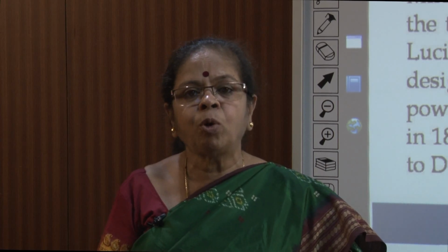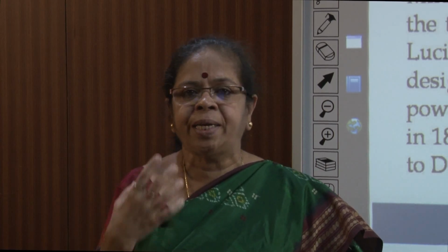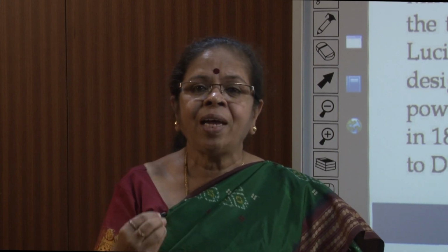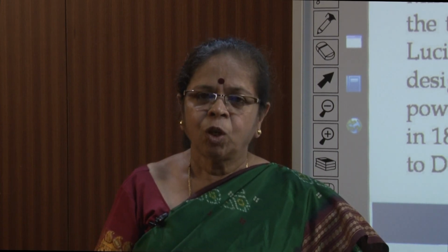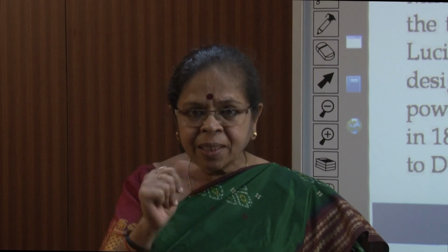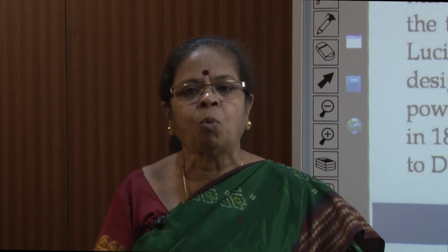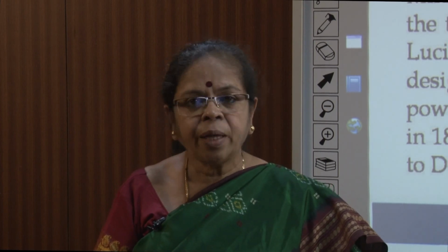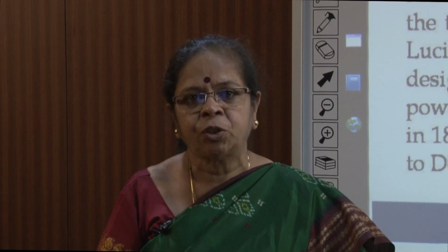So E is proportional to N d phi by dt. So if I use DC, phi is a constant. Except in the instant where you just apply the DC voltage with a switch, the flux is a constant and therefore cannot induce voltage.